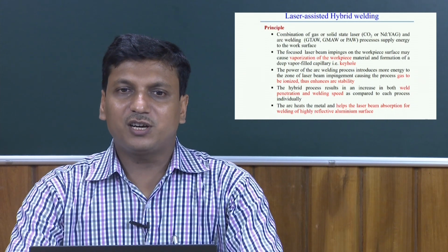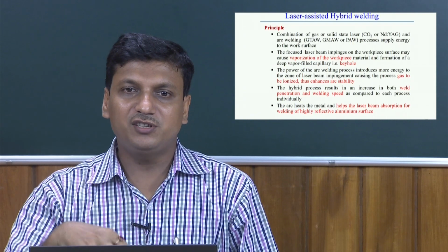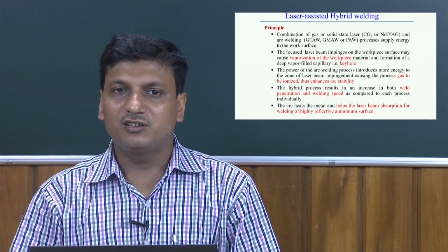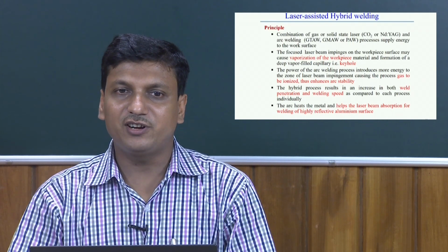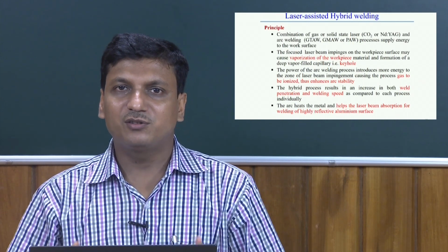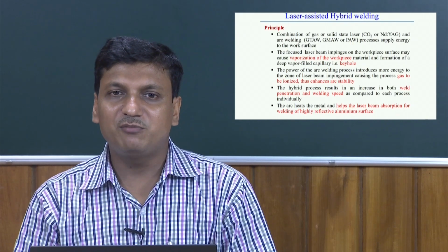First, the focused laser beam impinges on the workpiece surface, and that may cause vaporization of the workpiece material, which finally forms a vapor filled keyhole. That means the keyhole mode is mostly used in hybrid laser welding.